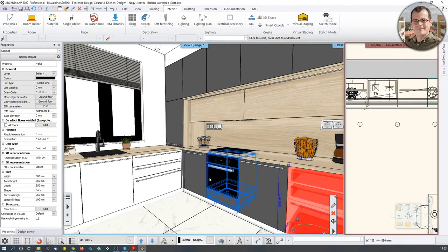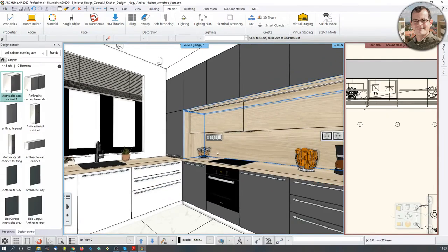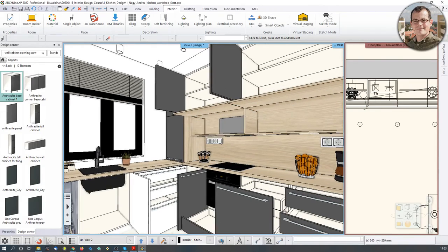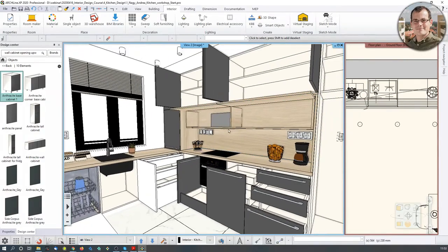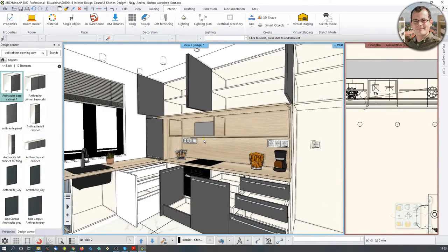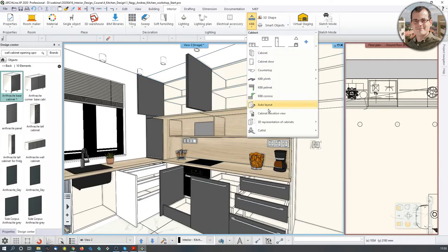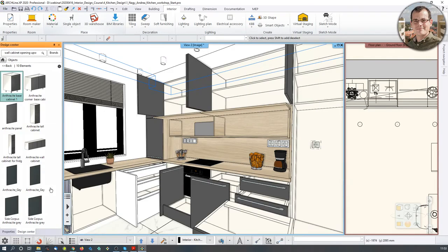And if I now use this, sorry, Control Shift O, then the cabinets should be opening in any second now. It has a lot of them, so yeah, that's how you do it. It's a very good way to show how your drawing looks like. I don't know if this would close them back, because for that you need to use another tool. So if you want to toggle it back and forth, then make sure you shortcut the close door as well. So I'm just going to undo this now.